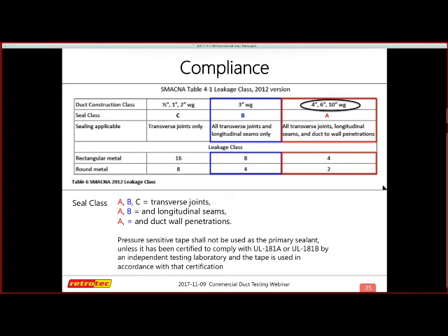You really should be sealing them all the time, even though it's low pressure. You really should be sealing everything. This includes spiral ducts also, in terms of all of those joints really should be sealed, because that's part of your longitudinal seam, and they do leak. They may not look like it, but they actually do have leakage.